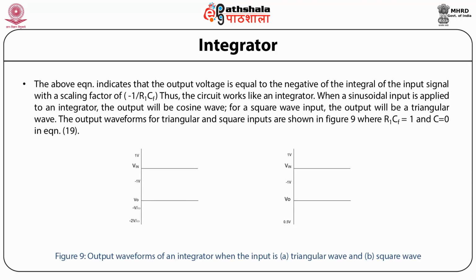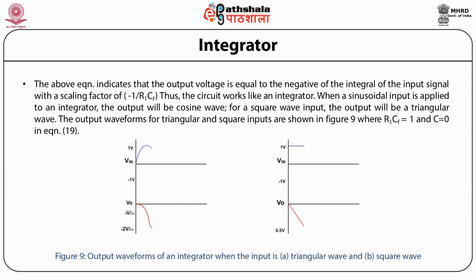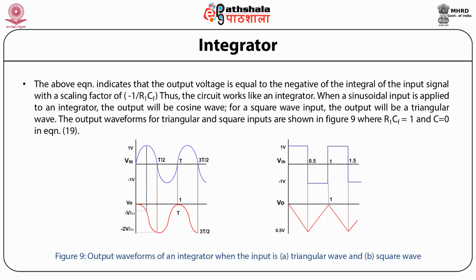The above equation indicates that the output voltage is equal to the negative of the integral of the input signal with the scaling factor of minus 1 divided by R1 CF.